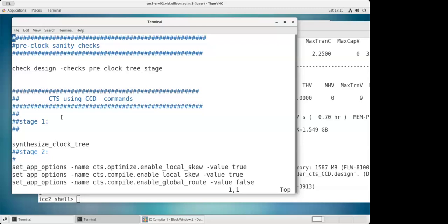Now, if you remember when we were talking about the clock, I mentioned very clearly, the clock edge should reach each and every flip-flop at the same time. Remember? Now there may be a possibility, there can be a difference. They can reach in a different time. But it should not be like, okay, one edge is reaching at one flip-flop at 2 nanosecond, other is reaching at a 10 nanosecond.